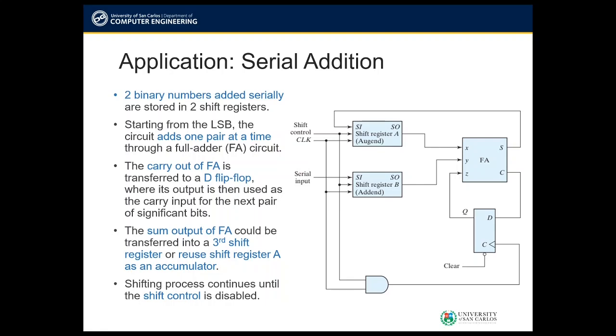If you have an IC with limited space, using serial operations would have the advantage of requiring less silicon area on the chip. To mitigate the slow serial operations, another alternative is to use a faster clock frequency. To demonstrate the serial mode of operation, here is a design of a serial adder.